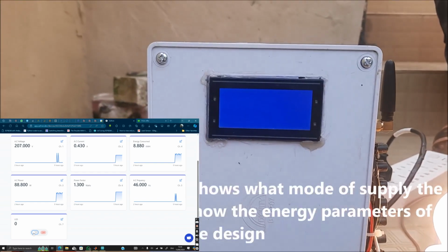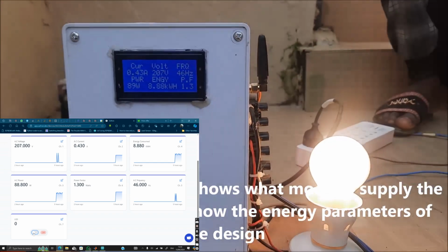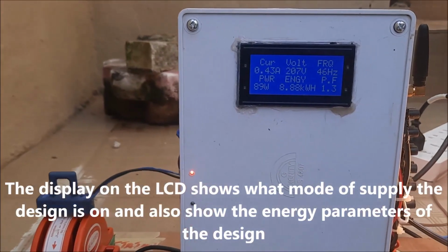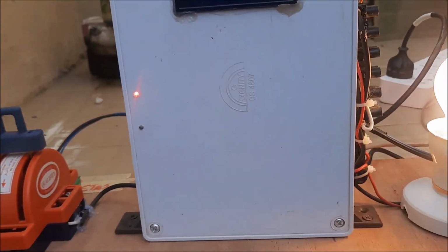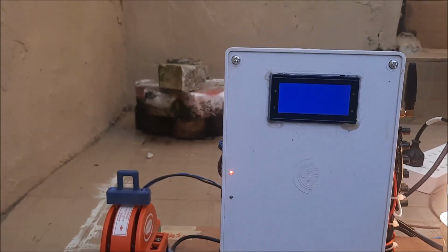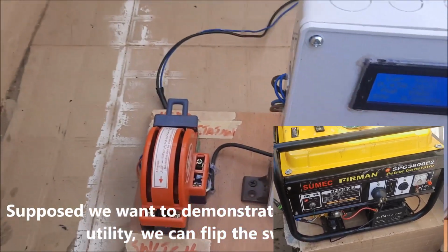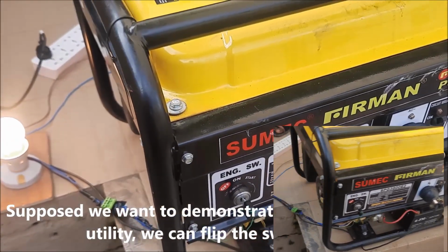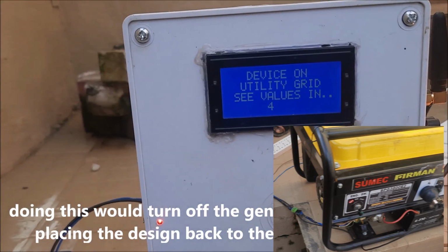The display on the LCD shows what mode of supply the design is on and also shows the energy parameters of the source. Now, we try simulating for when the grid power has been restored by flipping the knife switch to the utility grid source. This would automatically turn off the generator and transfer the power supply to the grid source. So it has turned it off now. And it's on utility.